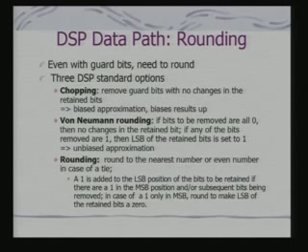So, effectively, if I take a decimal case, I am adding 1 to the retained bit not just for 1 0 0, I am doing it for 1 1 0 and 1 0 1, and I am adding 1 to the LSB. So, I am approximating the thrown away bits by adding 1 to the previous retained bit. If it is 100, it is actually a tie.